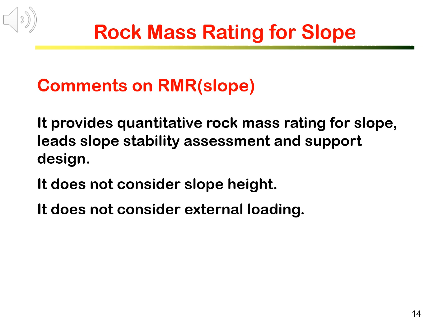The IMR slope system does not consider external loading such as machines and buildings on the top of the slope. If the slope is subject to such loading, then the loading condition must be considered in stability assessment. Similarly, if the slope is close to blast or is subject to potential earthquakes, then the effects of blast and earthquake loading should also be considered.